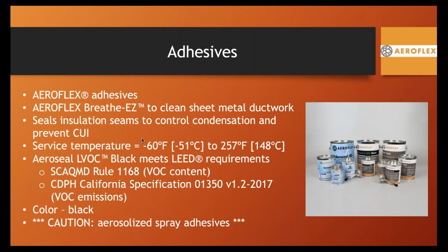With elastomeric, water-based adhesives should not be used. Something with low solvents would be the right alternative. And most HVAC adhesive manufacturers do offer a solution for elastomeric.